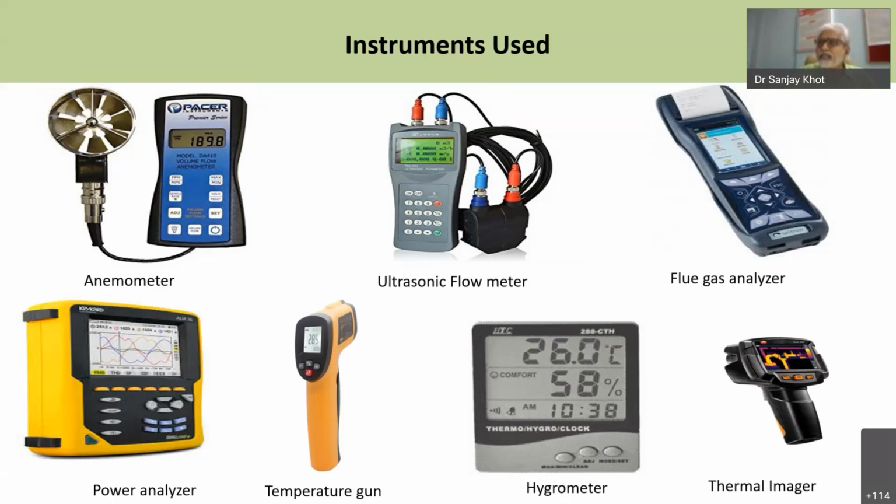Even sometimes when electricity flows at higher than the rated current, the cable gets heated, and once it is heated for a long time, there are chances of a short circuit, but it is very difficult to notice with the naked eye. With the help of this thermal imager, we get the actual real image as well as the thermal image, and by that we can calculate the temperature loss, the heat loss because of radiation.